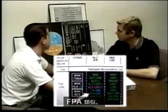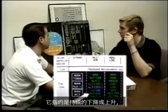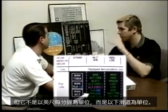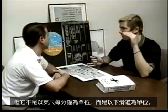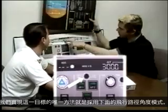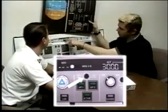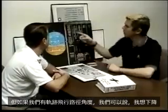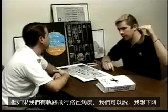FPA is similar. It's referencing a constant descent or climb, but instead of referencing feet per minute, it's referencing a glide path. The only way we can get that is by being in the track flight path angle mode down here, and this currently indicates heading vertical speed. But if we had track flight path angle, we could say, I want to descend 3 degrees.